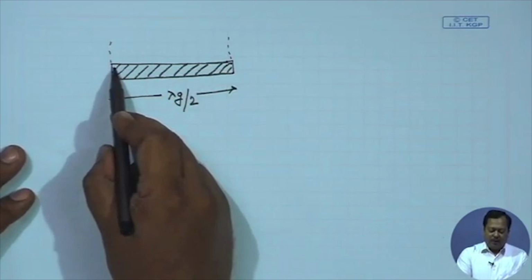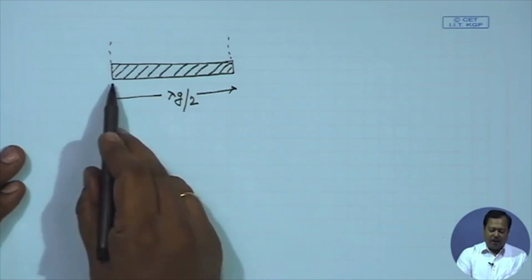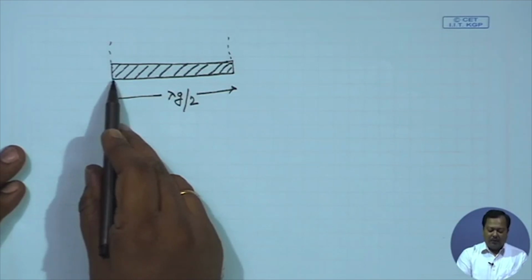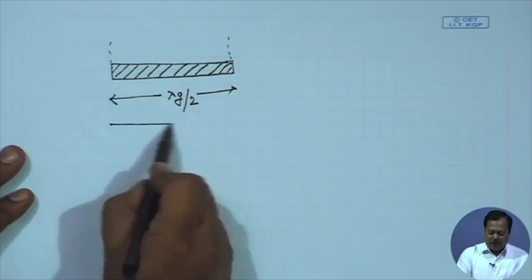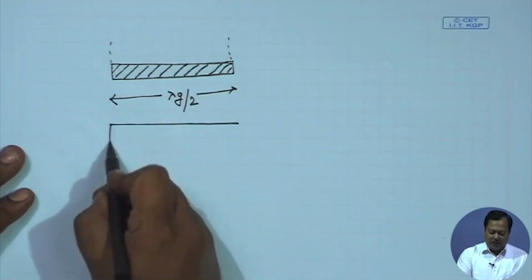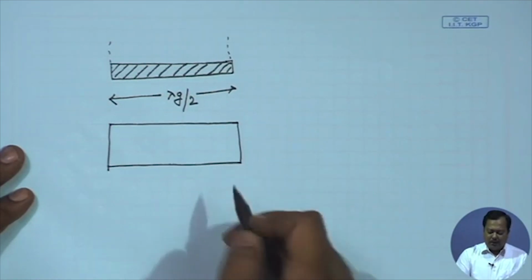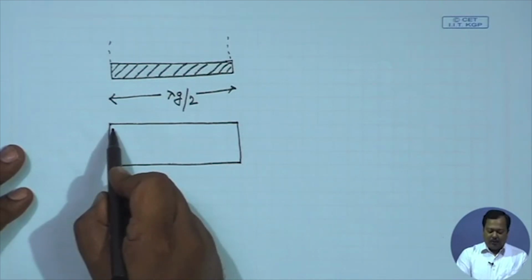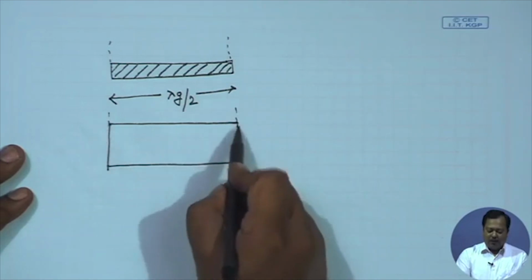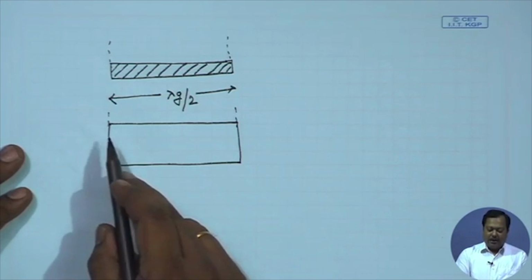From the fringing field, if the electric field and magnetic field are in the same phase, there will be some radiation. Practically, what we see is that if we keep increasing the width of this microstrip line resonator, then the part of magnetic field and electric field on these two planes, which is in air and in the same phase, increases.